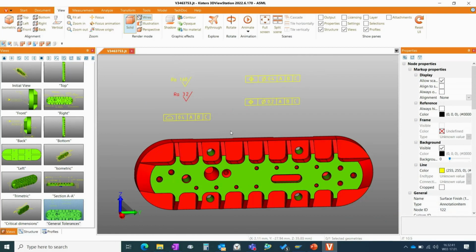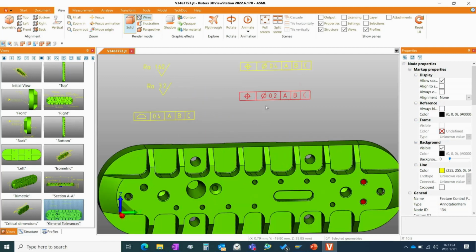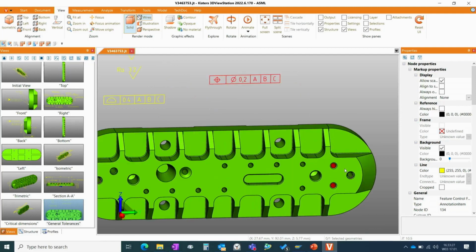This is not only important to make the reading more convenient, it's very essential if you think of the next phase of the 3D PMI way of working, for all the downstream applications, like CMM or also CAM, if you use the PMI for this. It's very important that this software is able to electronically process the PMI, so that there's really a relation between the text of the PMI and the geometric feature where this text is related to.